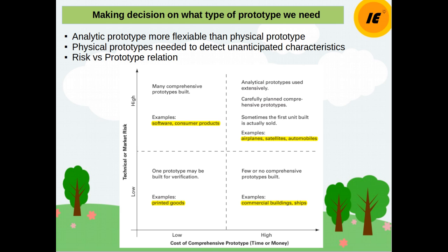One reason for this surprise is that all of the laws of physics are operating when the team experiments with a physical prototype. Physical prototypes intended to investigate purely geometric issues will also have thermal and optical properties. Some of the incidental properties of the physical prototypes are irrelevant to the final product and act as an annoyance during testing. However, some of these incidental properties will also manifest themselves in the final product. In these cases, a physical prototype can serve as a tool for detecting unanticipated detrimental phenomena that may arise in the final product.